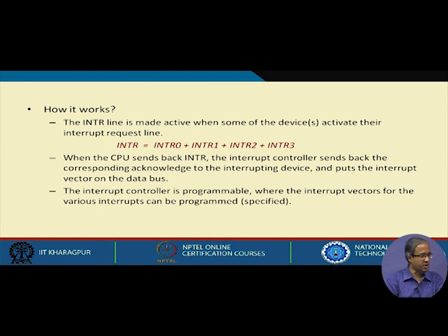So, this is the second step, and the third point to note is that, as I said, the interrupt controller can be storing the interrupt vectors for the different devices. So, the interrupt controller is in some sense programmable. Programmable means before you are using it, you can specify that these will be the interrupt vectors for the 4 devices. The CPU can initialize some internal register within that PIC, where the values of the interrupt vectors can be programmed or specified. Okay? Fine.